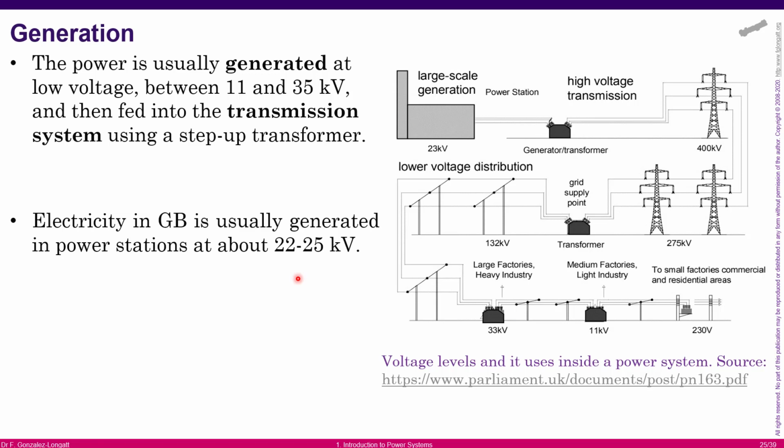and then we use step-up transformers. You must remember that the transformer was a key component in the evolution of the AC system, because it allows us to modify voltages and currents, especially to increase voltages for long distance transmission of bulk power, and then we use that high voltage at the local installations to be reduced and then distributed to your houses.